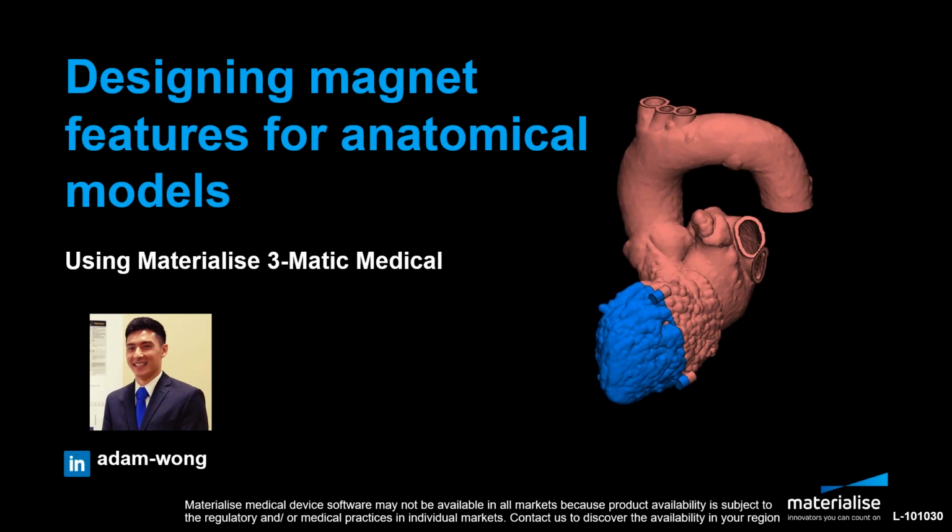Before we print a model like this, we recommend that you understand the limitations of your printer and material. For example, if you're working with a flexible material, we recommend that you print out maybe a smaller sample size before printing an entire model, mainly because if you're working with magnets and you're gluing the magnets in a magnet holder, or a feature that we'll show in this demonstration, you want to test the clearance that you need as well as the glue that you're working with, and that will save you time and money in the long run. With that, let's get into the demonstration.